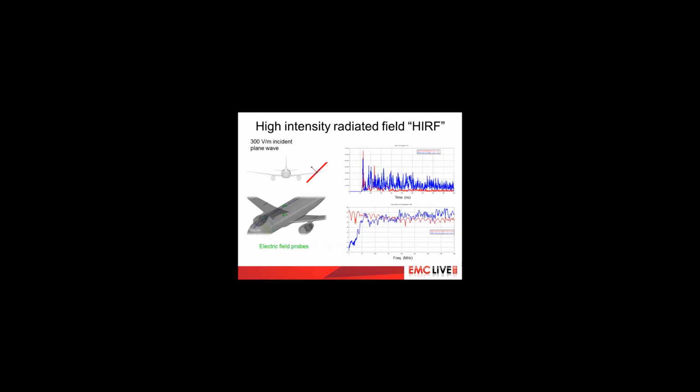Okay, in the last few slides, I would like to just introduce the topic of high-intensity radiated fields, or HIRF. This is also an important consideration for aircraft-related electromagnetic environmental effects. Aircraft have to fly in severe electromagnetic environments, due to the man-made fields from high-power transmitters such as TV, radio, radar systems. And the spectrum ranges from 10 kilohertz to 18 or even 40 gigahertz.